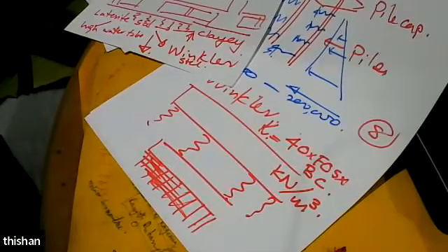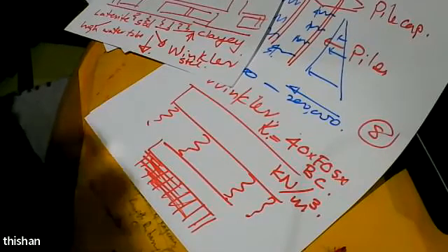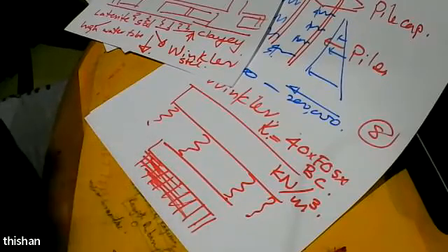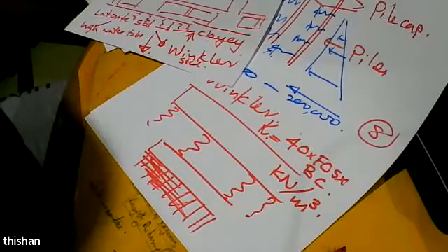But you can have pre-stressed concrete flat slabs. Pre-stressed concrete flat slabs are not cracked, because pre-stressed means the full section is effective, so you don't get cracking.